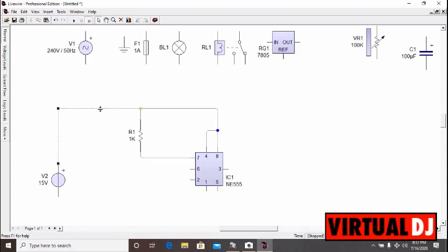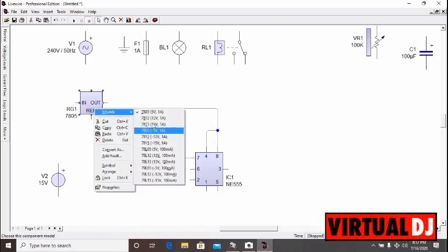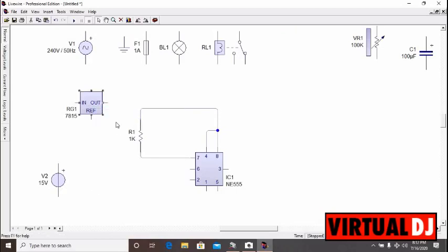Oh, before connecting to the positive terminal, we need to connect our voltage regulator. So I'll be using a voltage regulator of 7815, which is the voltage regulator for 15 volts. Then I'll be connecting my fuse to my DC supply, a 1 amp fuse. This is just for protection, it's optional. This section is optional, you could add it to yours.